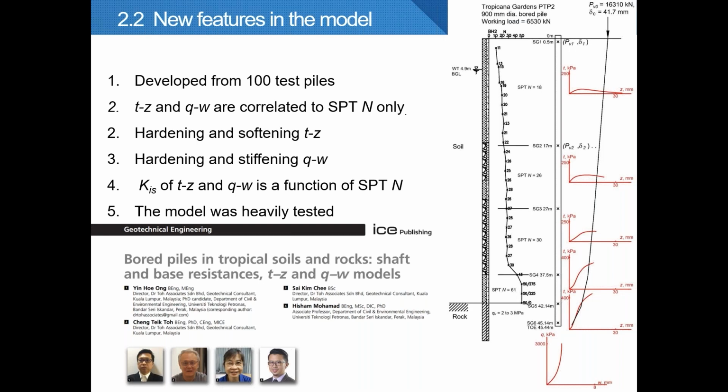Number four, the best thing about this method is that you can calibrate the parameters for this model using the data from your instrumented test pile. You can find the details in our paper published in Geotechnical Engineering, ICE, UK.